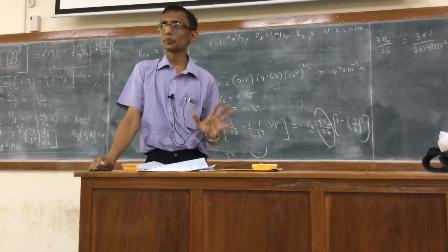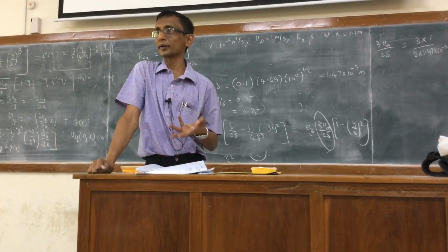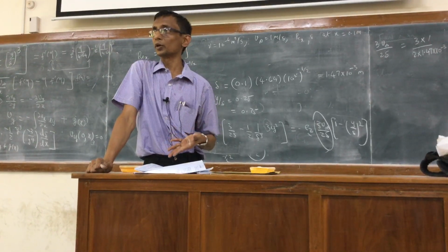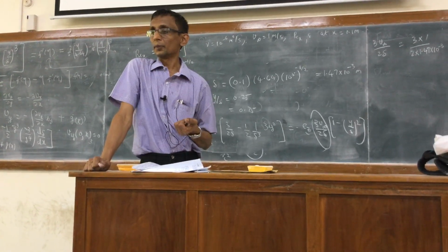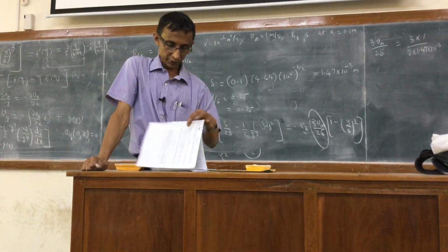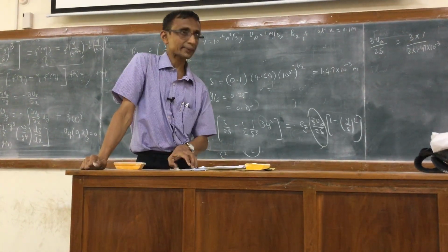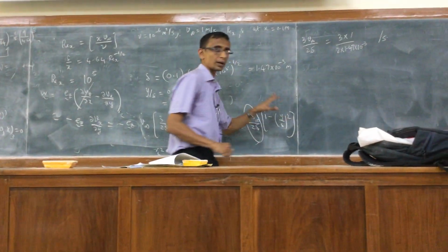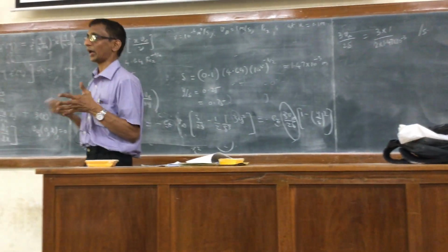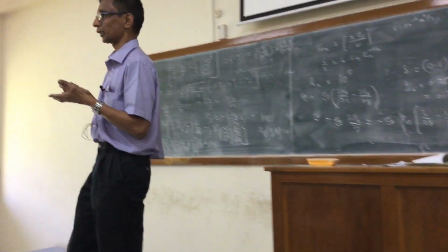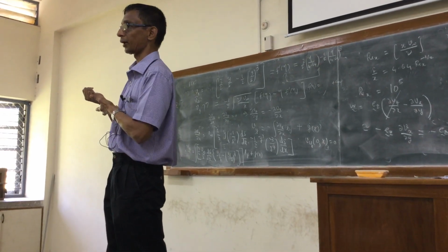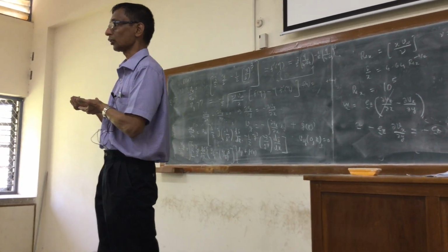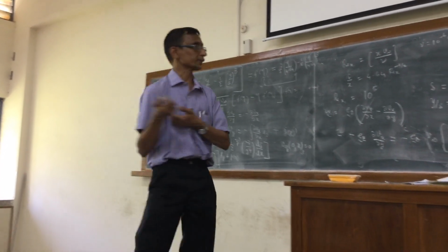I think we are more worried because we have seen the vorticity is created at the boundary by the no-slip boundary condition, where you get the maximum difference in velocity. So that is the maximum vorticity, and you can clearly see that this approximate formula simply vanishes at y equal to delta. So at the boundary layer edge, it becomes 0. So there is a diffusion of vorticity, right?